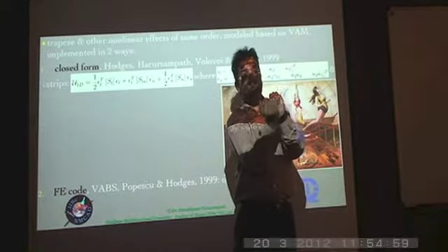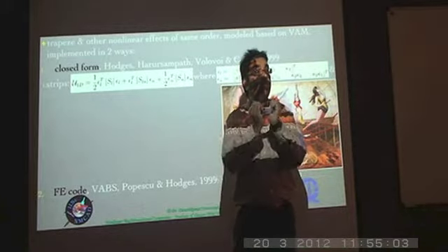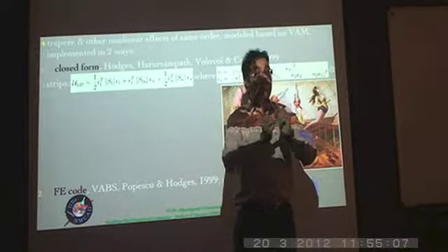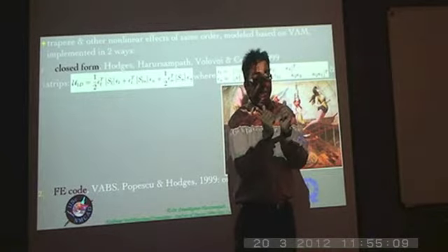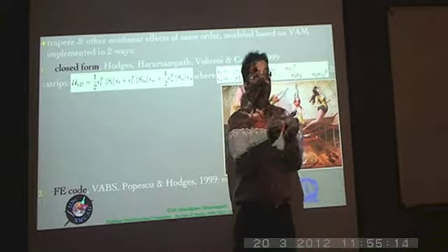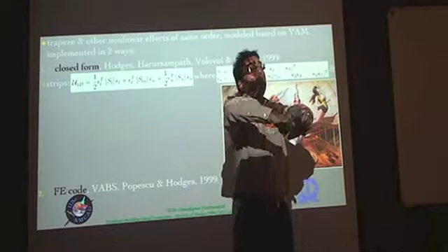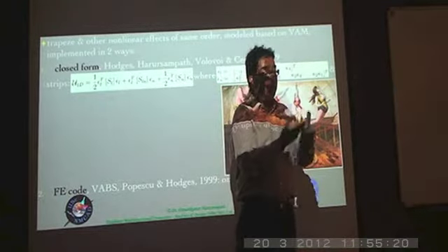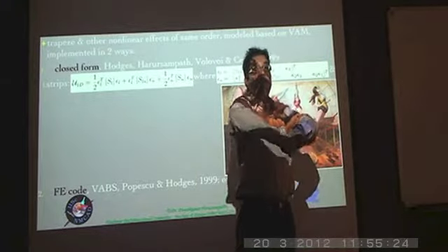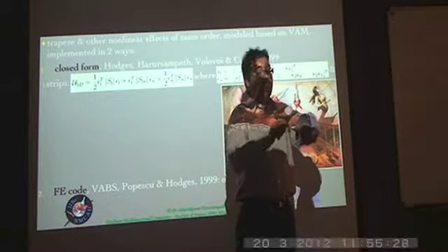from common sense. And so you basically see that the kind of curvatures that you can get in this particular direction are very small, whereas the kind of curvatures that you can get in this direction are much larger. So the nonlinearities associated with larger deformations are more prominent compared to the nonlinearities associated with smaller deformations. Again, it's the same case with twist, because this is similar to an open cross section. The torsional stiffness is very low and you can easily twist it, and it can have very large twisting curvatures, or in other words twist per unit length.